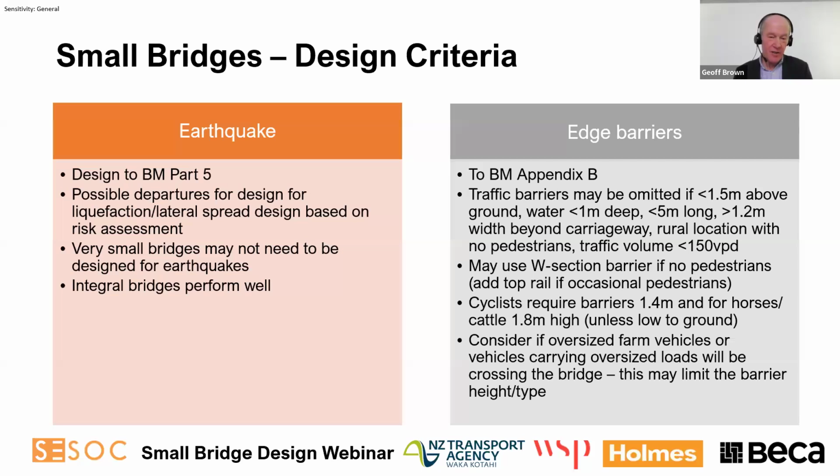If the risk to human life is low, and if they're not going to move very far or collapse, then you may not need to take special measures. And it's worth noting that integral bridges perform very well under earthquakes. Edge barriers are normally designed to the Bridge Manual Appendix B.